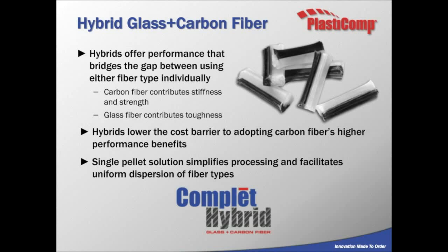Hybrids are a lower cost option than carbon fiber, and it's a single pellet solution. And we can tailor the material to the performance requirements needed. So we can vary the total percentage of the reinforcement level, and then we can vary the proportions of glass and carbon to, again, tailor it to the application requirements.